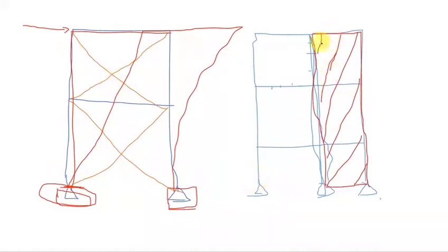Even if you come to concrete structures, this shear wall here will be acting as bracing. It will be taking the lateral loads, so that even if you apply a lateral load at this point, then if you have this shear wall, this member will be so rigid. The rigidity of a shear wall tends to infinity. That means it is too rigid compared to columns. Why is it too rigid? Because it is very deep.